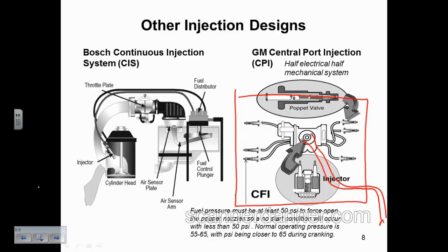So there'd be a connector out here. I even remember the colors of the wires. It was blue and red. So I could check for injector pulse, and it was good. And I checked fuel pressure, and I had 49 pounds of pressure. To me, 49 pounds of pressure is enough to run any multi-port system I ever worked on.